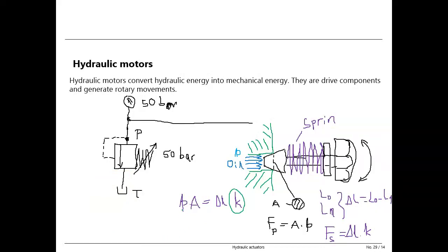And you can easily follow that here in these equations. Spring constant is constant, and the area is also constant because we cannot change the cross-section area here. I show you that the cross-section area here, I mean this one here, we cannot change because it depends on the geometry. It is already selected and designed, so we cannot change it. And in these equations there are two parameters. On the left side pressure, on the right side is length of the spring. So that means by changing of the length of the spring, we can change the pressure.